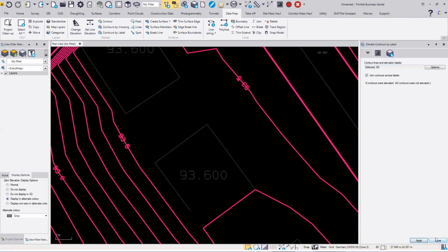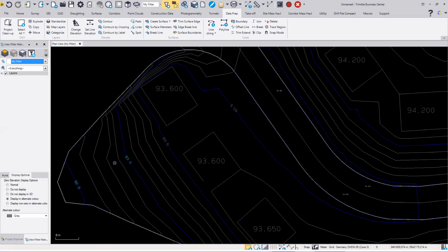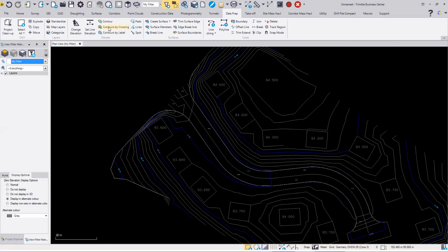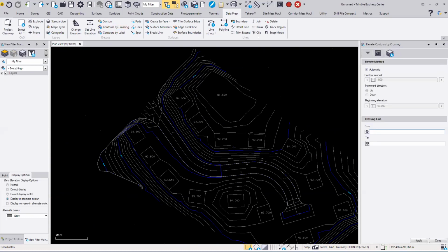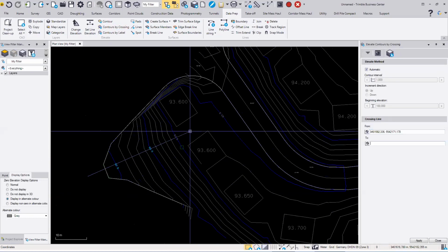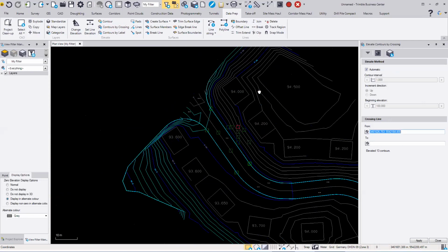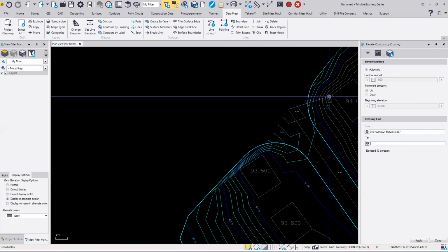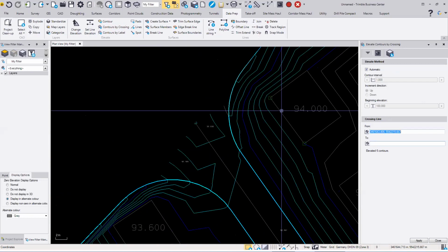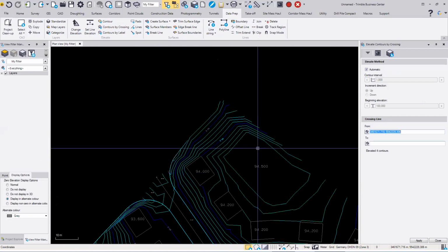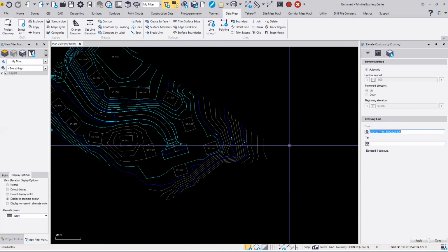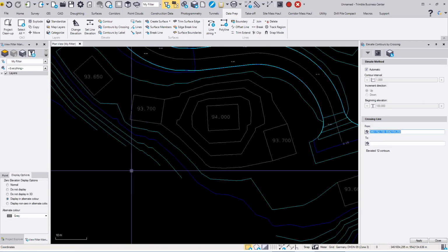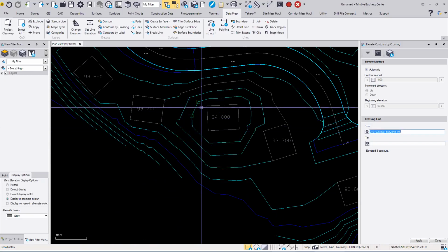I apply this, and now it's automatically elevating those lines into 3D based on the text. All the lines in between, I can also just elevate by crossing. So Business Center is automatically interpolating the elevations for those lines. So just quickly go over, and we can do one verification at the end. So this is done.